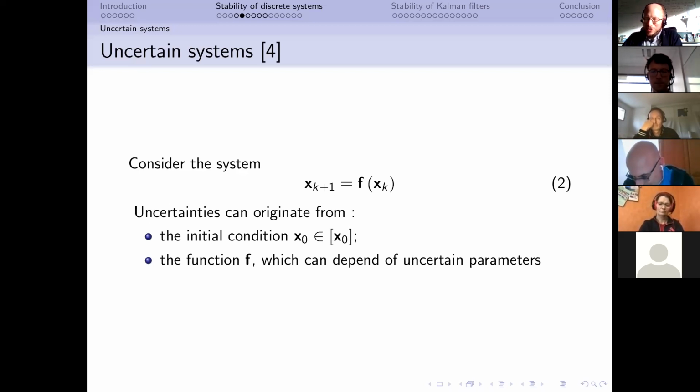And usually what I tell everyone is, take the measurement noise as a parameter characteristic of the sensor, use it from the data sheet or perform an experiment and keep it fixed. And the only tuning parameter then should be the process noise covariance. Do you aim at using your approach as some kind of building block in an optimization scheme that allows you to tune the process noise covariance to enhance the robustness?